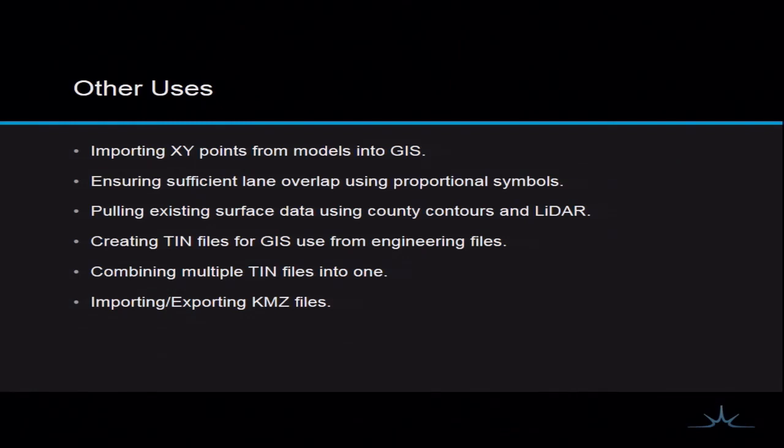There's other forms of use that we have here. One of the other important ones that I want to point out is exporting your desktop or your MXD as a KMZ file, because not everybody has GIS. So it's really easy to share what you're seeing in your program with people who don't have a GIS license, and vice versa. You can bring files in that you get from consultants or from the DOT straight into GIS as a layer.